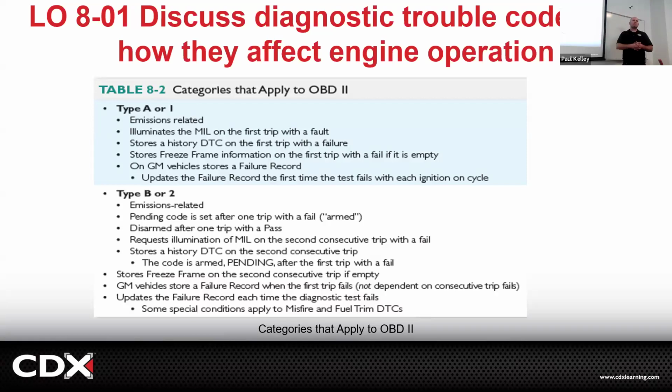So if I get a code and it's a code for a misfire, but maybe it's not happening right now, I want to know what was happening when the code set. And there are instances where I go in and it says vehicle speed 117 miles an hour, engine temperature 237, and I'm like, I drive it and it doesn't misfire, and then I go to the customer and say, hey, I know you got a misfire code.